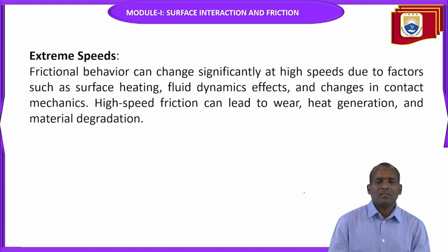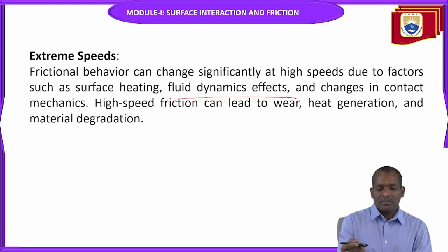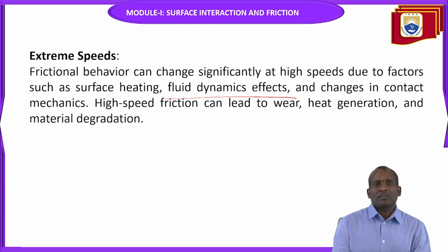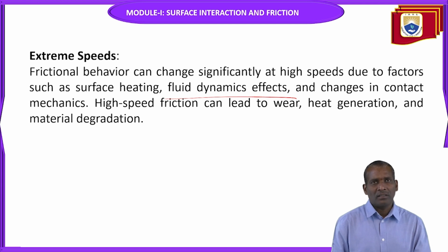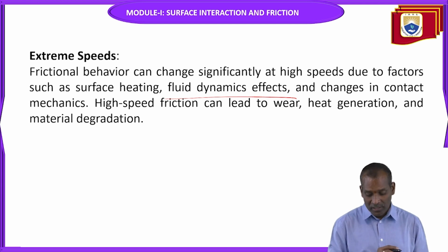All these factors lead to changes in contact area and contact mechanics. The frictional behavior can change significantly at high speeds, and due to fluid dynamics effects, material degradation is also possible. High speed friction leads to wear, heat generation, and material degradation. Like this, all factors lead to damage of the surfaces.